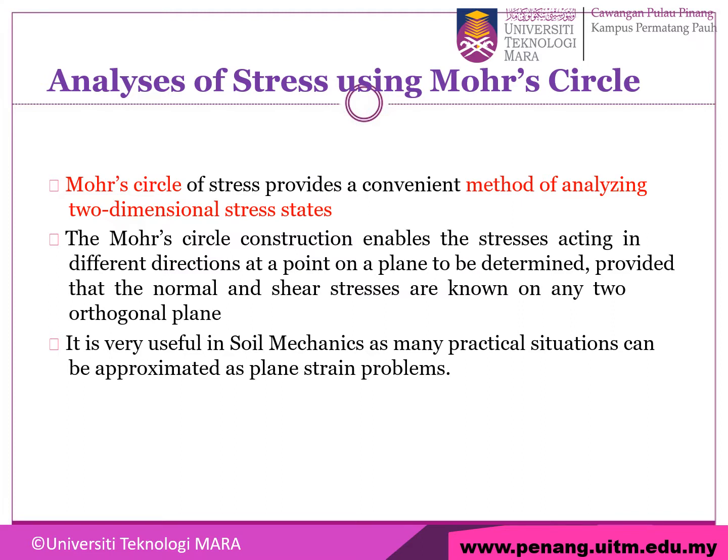Analysis of stress. We will use the Mohr circle. The Mohr circle of stress provides a convenient method of analyzing a two-dimensional stress state. The Mohr circle construction enables the stresses acting in different directions at a point on a plane to be determined, provided that the normal and shear stresses are known on any two orthogonal planes. It is very useful in soil mechanics as many practical situations can be approximated as plane strain problems.